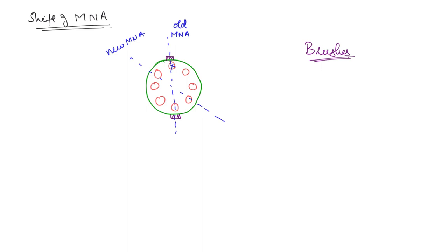So that means now current is flowing here. Okay, so now the brush is connected at the conductor where the induced EMF is not 0. Ideally, what should happen? The brushes should be collecting the current when the alternating current is at 0, right? But here what is happening? The brushes are collecting the current when the current has not yet reached 0. Okay, so that is the problem with the shift of magnetic neutral axis.